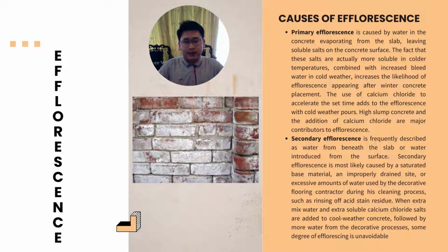by a saturated base material and improper drainage, or excessive amounts of water used by the decorative flooring contractor during the cleaning process, such as rinsing of acid stain residue, when extra mixed water and extra soluble calcium chloride salts are added to cool weather concrete, followed by more water from the decorative processes. Some degree of efflorescing is unavoidable.